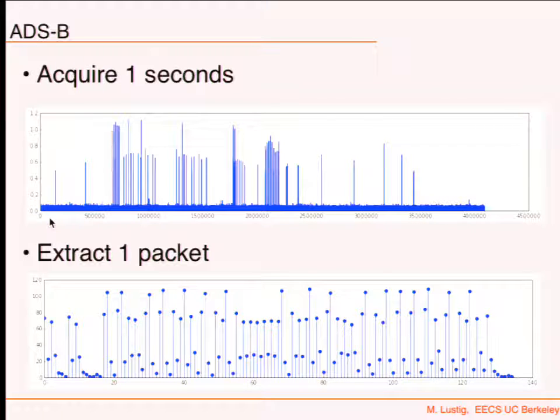One thing that's really important, if you're in the basement of Cory doing this work, obviously it's not going to work well. 1 gigahertz doesn't penetrate through buildings. So it's important that you be close to a window; a wooden house is okay. Go outside if you need to. You'll get better reception. These are also not great antennas for 1 gigahertz. They're okay, but not great. So just know that.